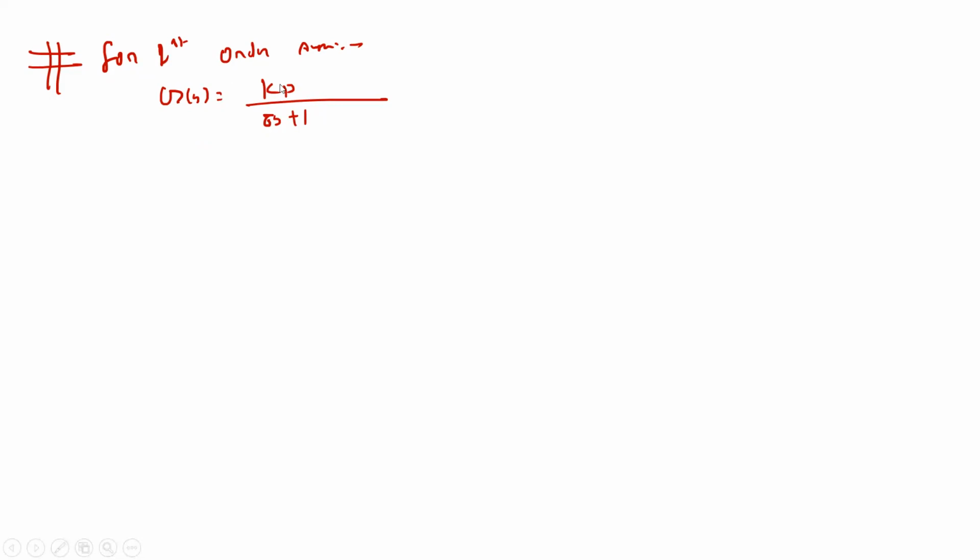Let's say if I want to calculate in terms of Kp as well, let's say this one is Kp. How can I calculate the amplitude ratio and phi? First you have to put s = jω, so I substitute s = jω in the denominator, τjω + 1.